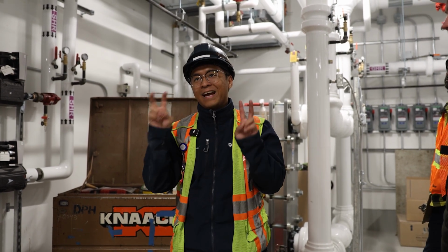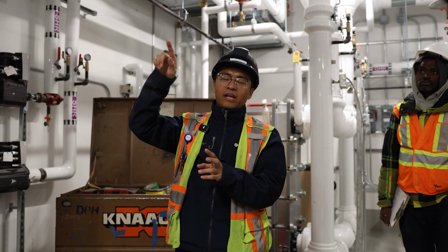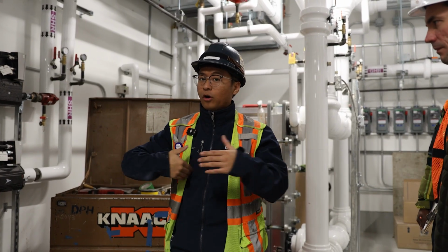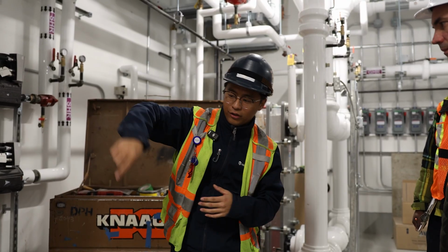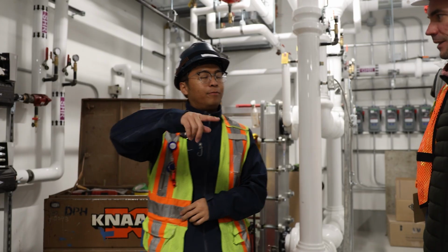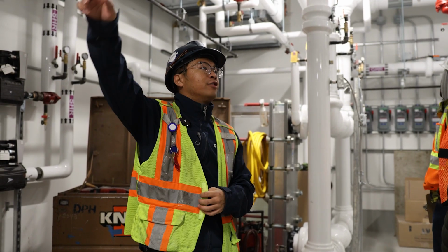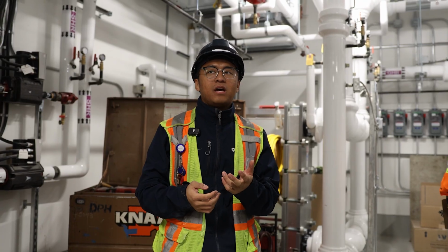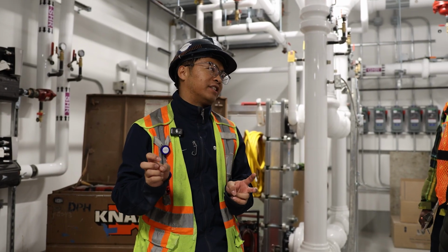So let's say at nighttime, the solar is not able to provide enough heat, that 3-way valve will open. So the solar will just do the recirculation mode. Yes, we will heat up the loop. So the heat will return to the solar. So 2 reasons. First is it's more like a solar energy efficiency, right?